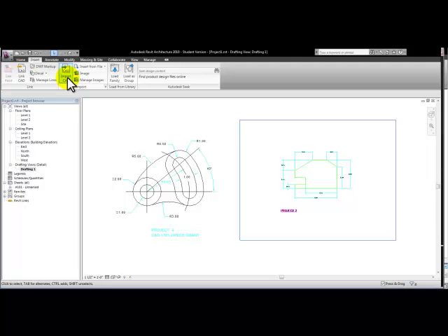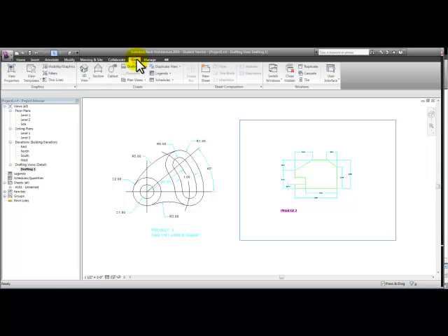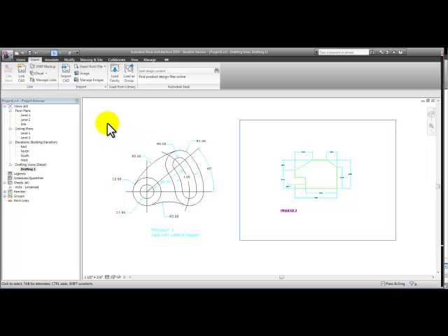If you're working on a detail sheet, you want to go to the View tab and create a drafting view. And that's what I did here. Creating a drafting view, we can bring all of these details into different drafting views and then use them on our sheet. In the Insert tab, we'll be able to link files, import them directly into our drawing, and also insert images.